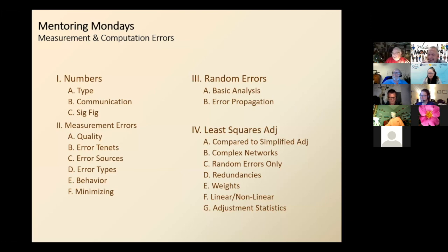I've seen monumentation set to replace a section corner and numerous quarter corners where the brass cap monument was within a foot and sticking up 0.8 of a foot above existing grade, and it cost me probably 8 months of waiting to do my survey while the other surveyor redid his to make it right, after I gave him the correct positions of the corners.